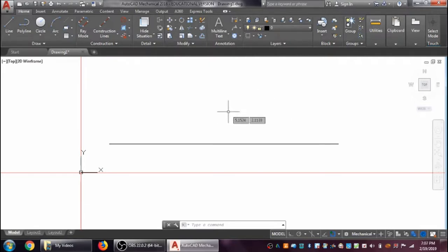We're going to do 6 total to represent each of the different line types that I want you to see here. So if you search around up here in your ribbon, remember in the home tab, we're going to go into the modify panel, which is right here. The offset tool is this tool here. So just click on that.